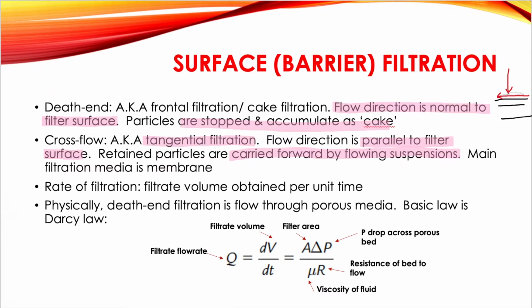To measure the efficiency of this filtration, we have the concept of rate of filtration. What does the rate of filtration measure? It measures the filtrate volume obtained per unit time. Physically, dead end filtration is flow through porous media.